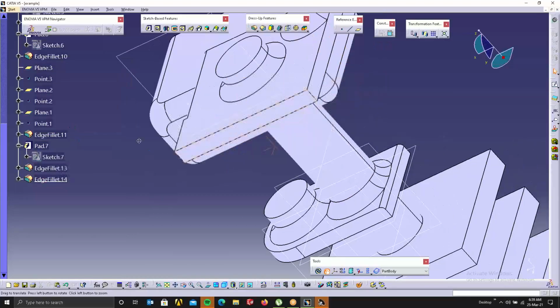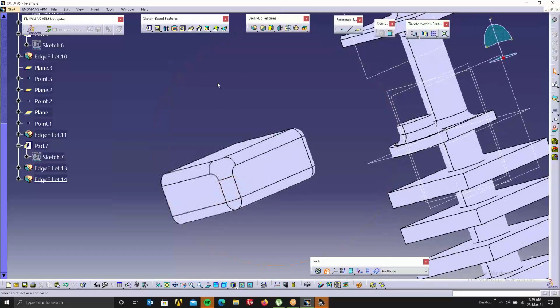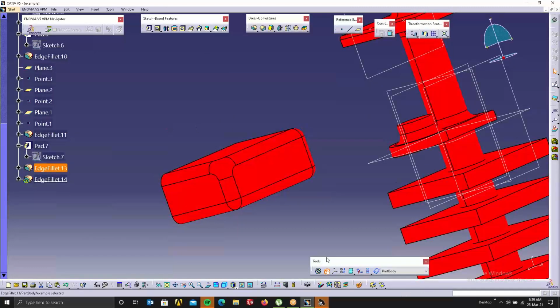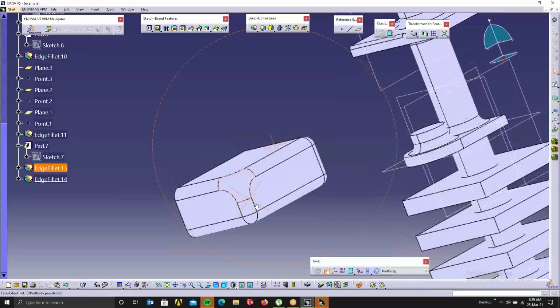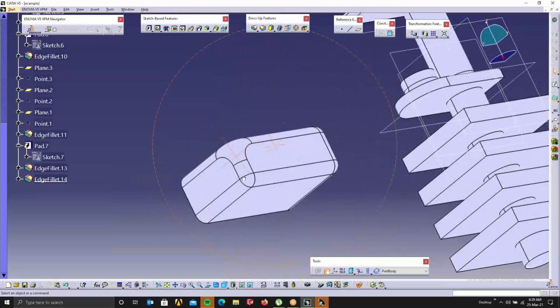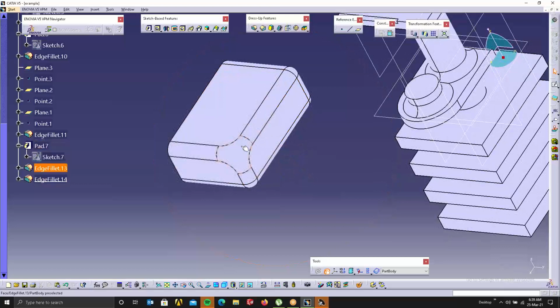Click OK. So you can see this is how the previous one was. But now with using setback values, you have a much smoother one, and plus you can increase it even further and click OK with the update. You can see you'll get much smoother edges compared to the other one, the conventional one. So this is your setback value. So have you understood this? Yeah. The things we discussed now are called the advanced filleting tools commands.